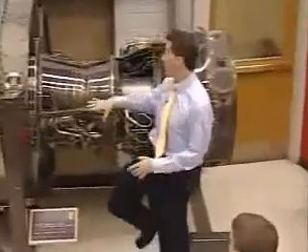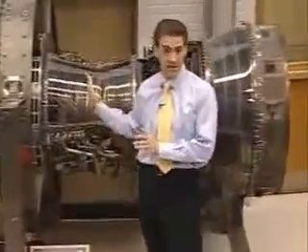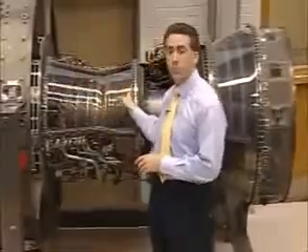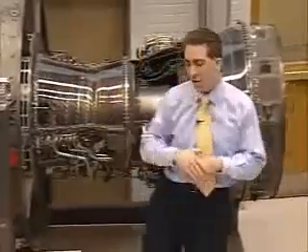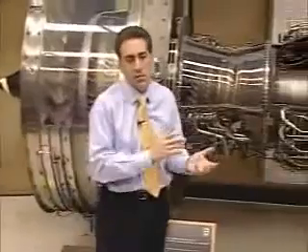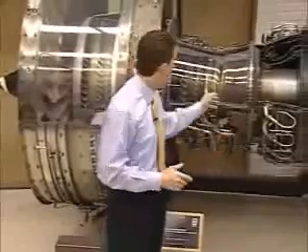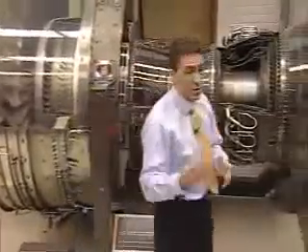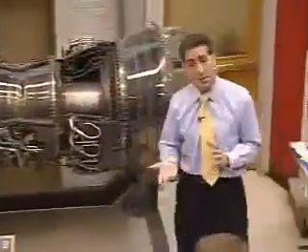You start out with a cycle analysis for this, so you determine how much pressure you need. Then you look back at your old engines and you say, for each one of these blade rows, how much pressure rise was I able to produce? And you know what those shapes used to be, and you know how fast you spun those blades as well. How fast you spin them is tied to your structural capabilities of the materials.